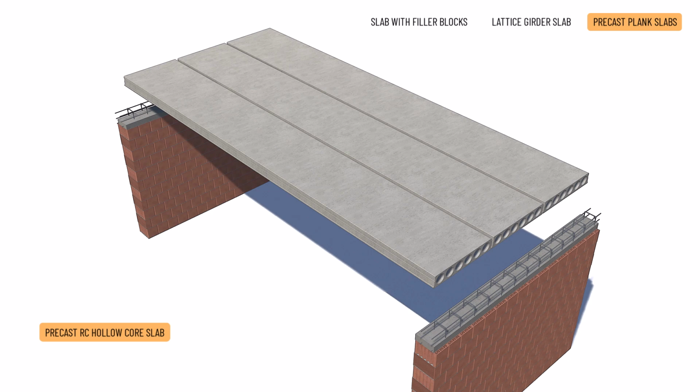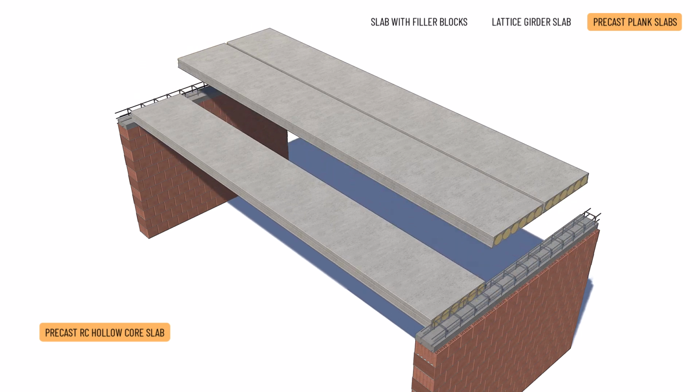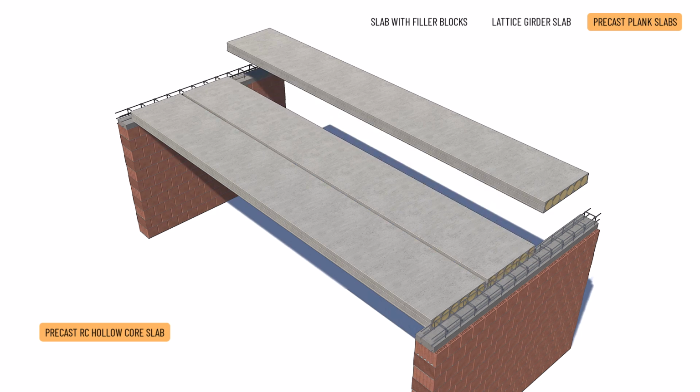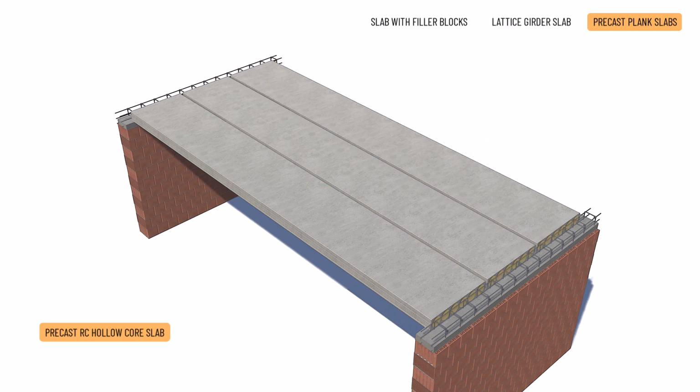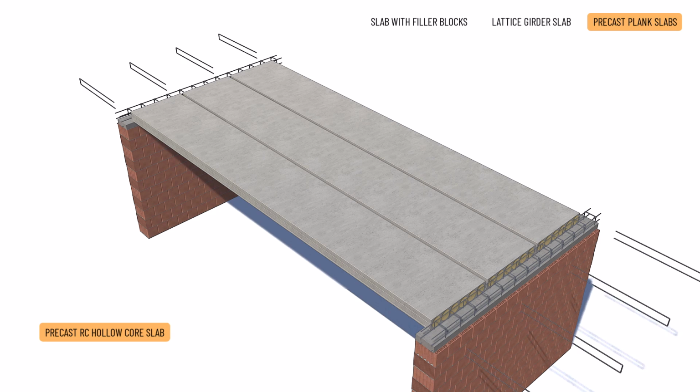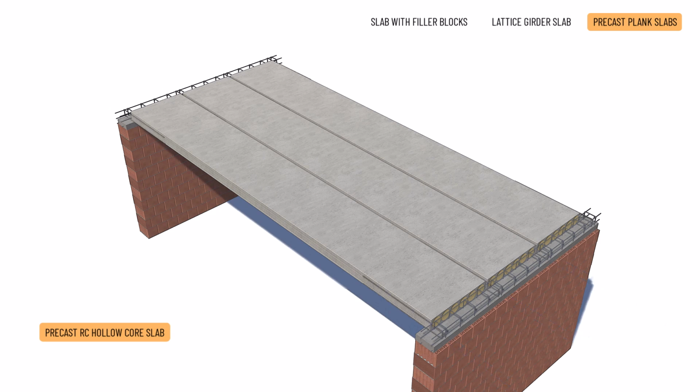The elements already have a considerable weight, but for this reason, the ring beam has to be made in 2 stages, first for the bearing, and then for the part coplanar with a top of planks. During the concreting process, the concrete must be kept away from the cavities using plastic plugs. Tie bars must be placed between the planks, ensuring that they act together with the ring beam.